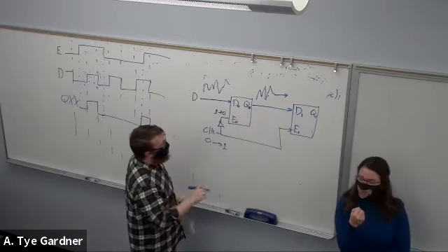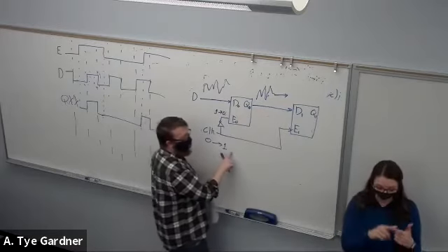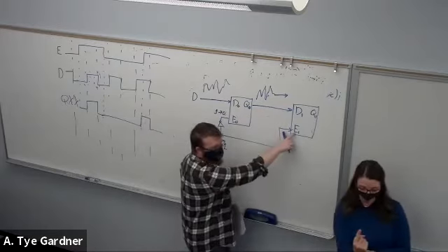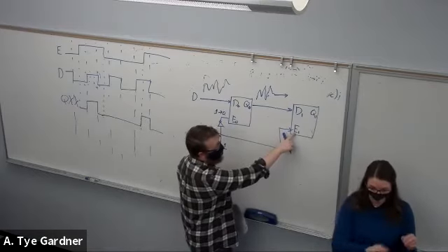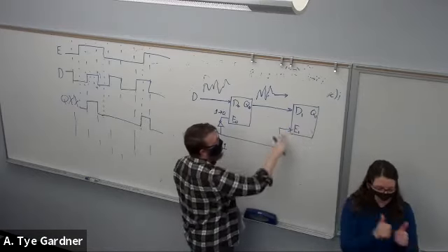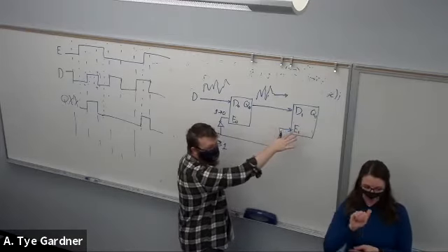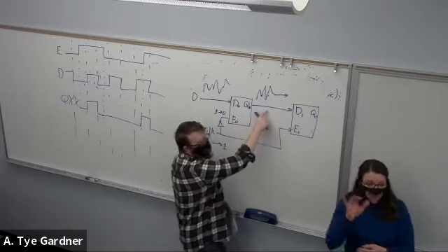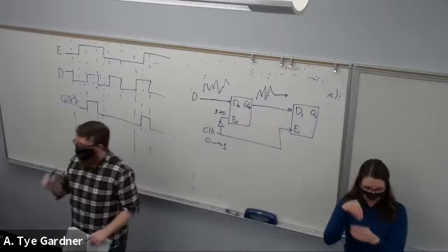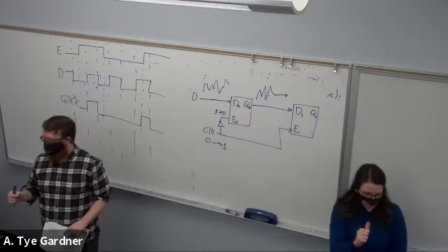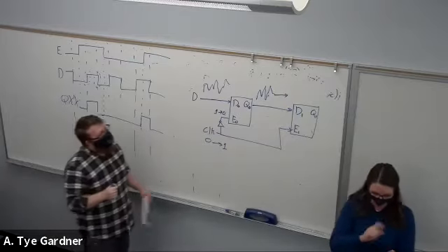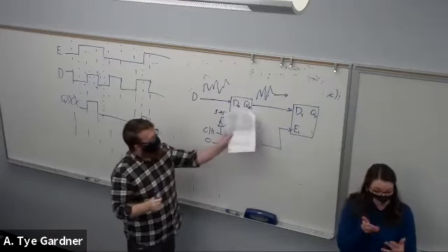Then the clock is now passing a 1 to enable 1. So the second D-Latch is now turned on, and it's transparent, but the input doesn't change. The input has no ability to change whatsoever. So even though it's transparent, it's been latched onto.